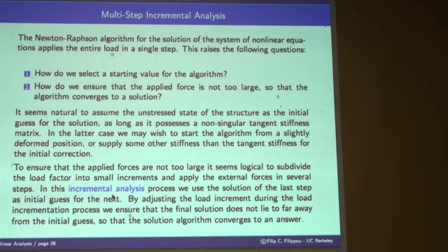And of course, displacement control, which displacement? You have to specify the degree of freedom you want to control, and so on. It's not necessary that it only be displacement. It can be energies, it can be other things, but many people call it displacement control. I like to call it load factor control, for the reasons I just illustrated.